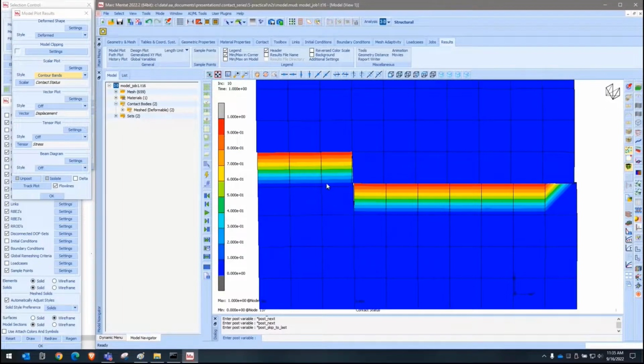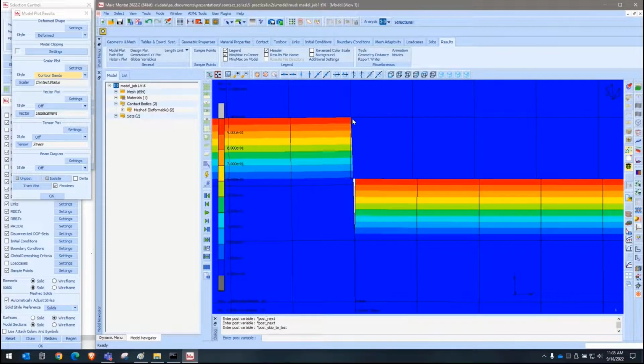So let's talk about why this happened. Firstly, this is node to segment. And since it's picked the bottom to the top, that node can catch nicely in that corner. So no surprise there. There's no node to touch on this face, and this one makes contact on that bottom face. So that's why the top part penetrates into this one, simply because we're taking contact from the bottom to the top. Even if it tries to do double-sided contact, it can't add this node from the top body into contact simply because that node and that node is effectively already in a different set of contact equations. So we'll form a circular dependency.